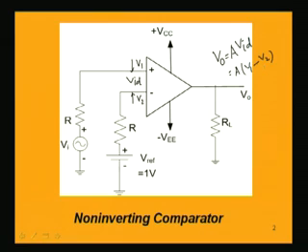Now, this op-amp has plus VCC and minus VCC supply voltages to be connected, as for all ICs, and we have earlier also discussed saturation, that is the output voltage cannot go beyond the supply voltage, which is typically plus 15 and minus 15 for 741 IC.